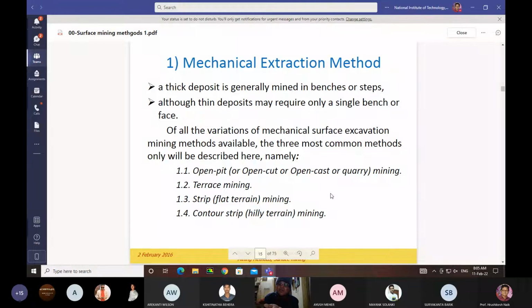And the shovel is more powerful. It cuts the material upwards. So that is the difference between a backhoe and the rope shovel. The rope shovel sits at the bottom of the bench and cuts the bench upwards, whereas the hydraulic shovel, backhoe, sits on the top of the bench and cuts the bottom bench. So that is the difference between the backhoe and a rope shovel.